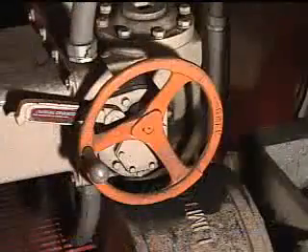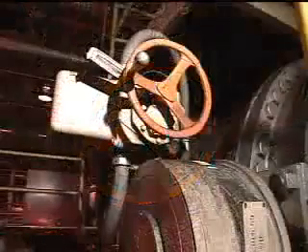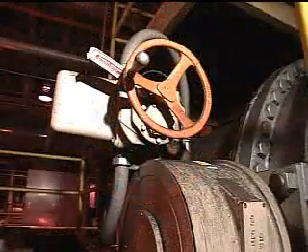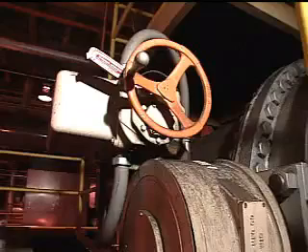For example, many circulating water systems use motor-operated butterfly valves as pump discharge valves. This type of valve is open when the pump is operating, but closed if the pump isn't operating to prevent any backflow through the pump.